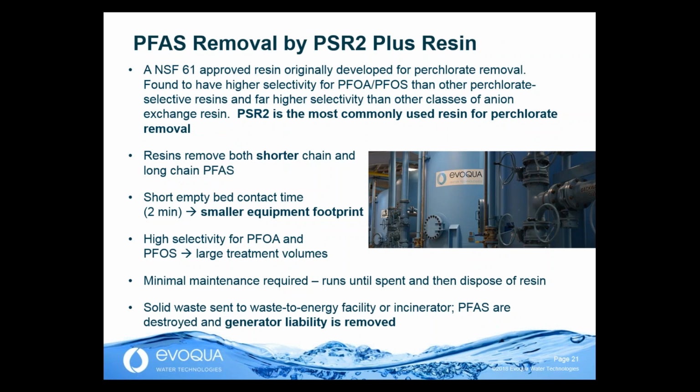So, with regard to PSR2+, what is it? Well, it's an NSF-approved resin. It's used extensively for perchlorate removal. As a matter of fact, in California, Massachusetts, and other places where perchlorate is regulated, it is the most commonly used resin, probably 80% of the perchlorate market it's used in. So the good thing about this is even though it's new, quote unquote, for treating PFAS, it's been used for the past 15, 20 years in drinking water applications for perchlorate removal at a very large scale. So there's a lot of experience with this resin.